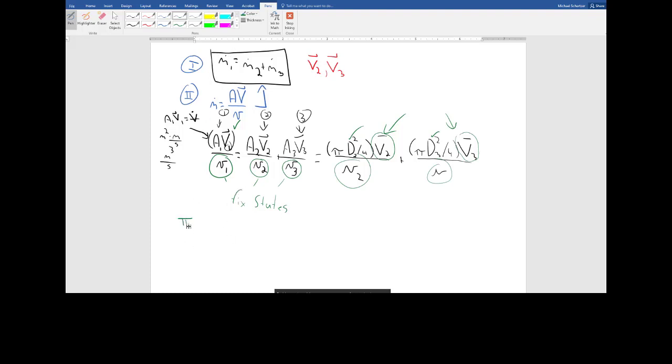If I go down here to equation 3, this tells me that 0.2 times m dot 1 is equal to m dot 2, which I could write, if I wanted to, as A1 V1 over specific volume at 1 is equal to 1 over 0.2 times A2 V2 over specific volume at 2.